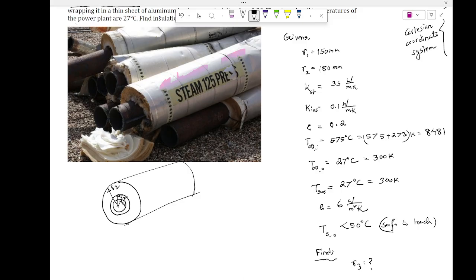And then these temperatures, okay? Like this is the surface temperature here, the outside surface, right? And then say this inside surface temperature, this TSI, right? And say you have at outside this T infinity, right? And this H here. And say the inside temperature, there is the assumption that you'll be doing here. You see, the inside temperature is the same as the steam temperature, okay? That's the assumption.